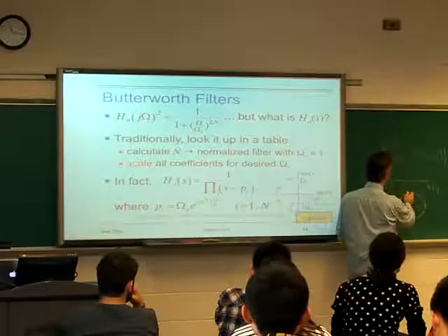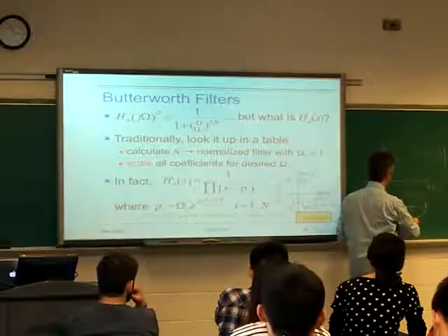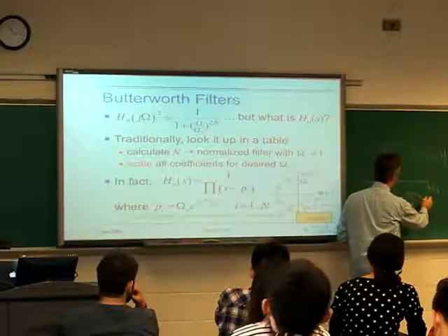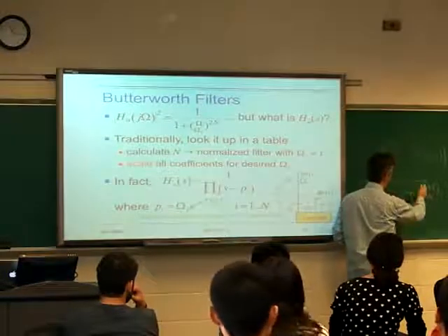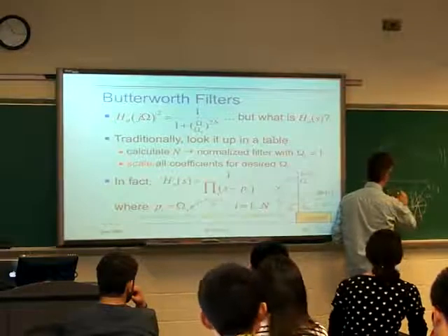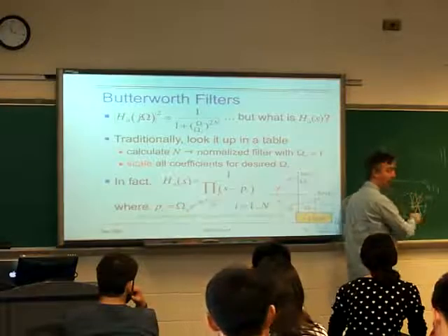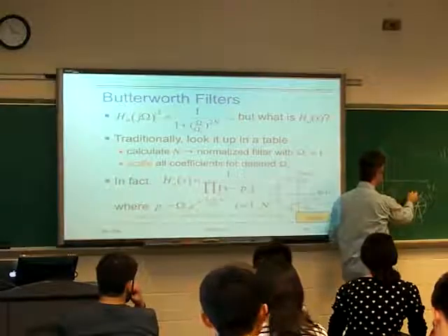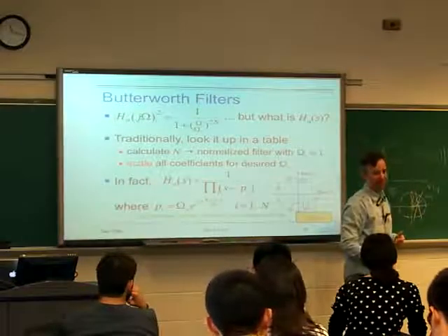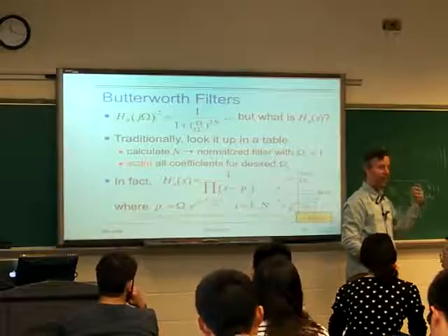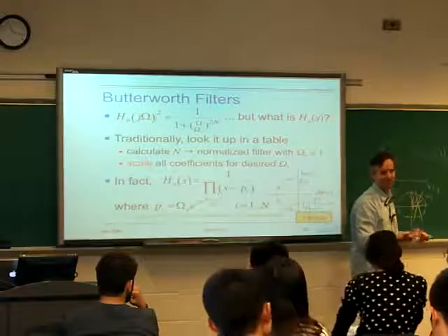It's like if you want to come up with a set of uniformly spaced poles on the unit circle, and I want to have n of them, then if I have 4n of these divisions here, and then I cross out this half, I've got 2n over here. And then if I want to avoid these ones, but keep it symmetric, then I should keep the odd-numbered ones. So then I just get n of them left. So I cross out every other one. I'm left with these n, and that's my half of my odd-indexed 4n roots of the 4n division of the circle.